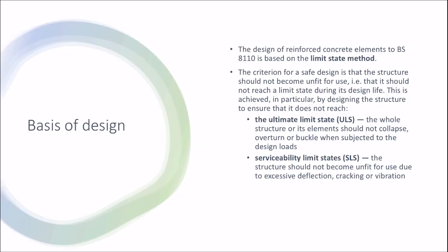Basis of design. The design of reinforced concrete elements to British Standard BS 8110 is based on the limit state method. BS is the British Standard, which is a standard, like MS is Malaysian Standard, and this one is for British. The criterion for safe design is that the structure should not become unfit for use, for example, that it should not reach a limit state during its design life. This is achieved in particular by designing the structure to ensure that it does not reach